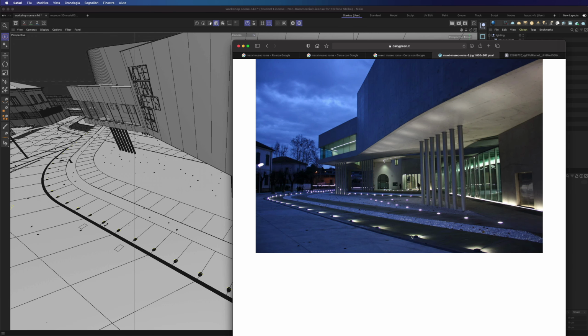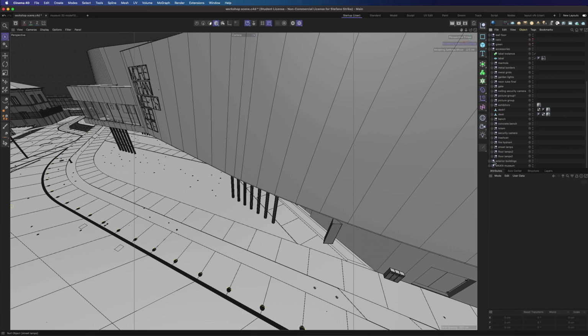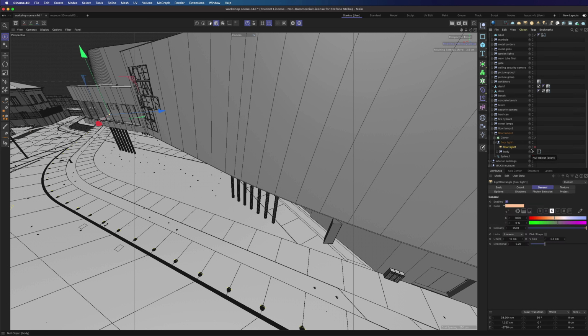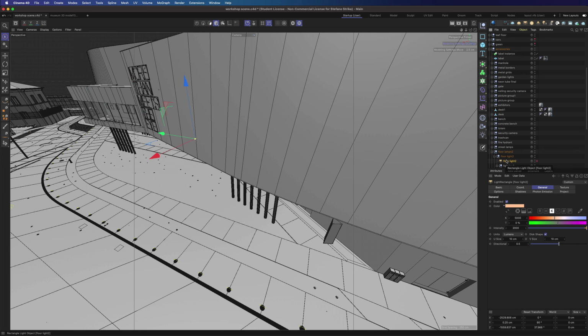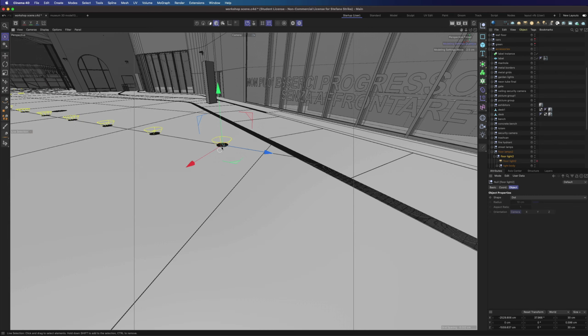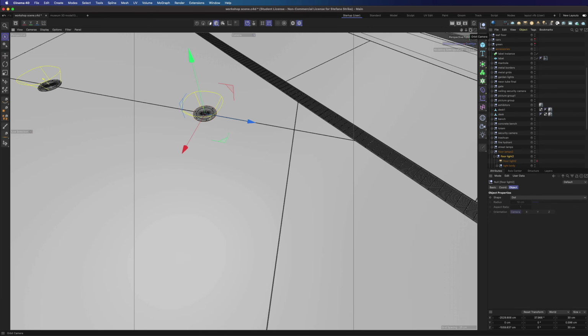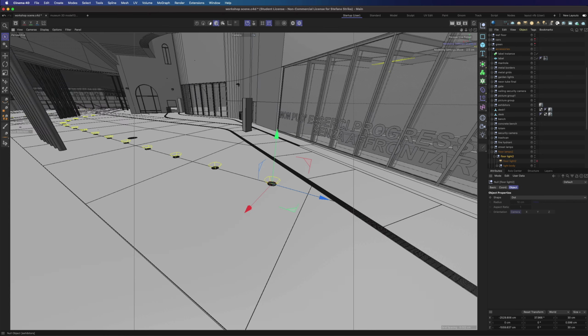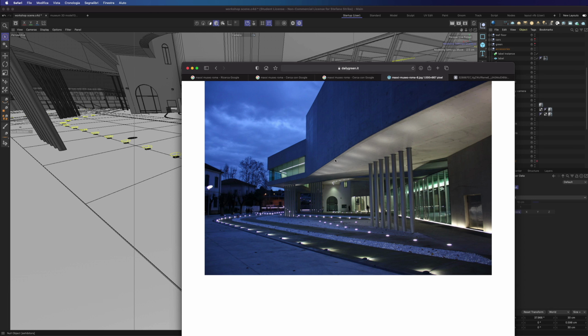Now we can see these floor lightings. In this case I always use a cloner to distribute them. I use 2500 lumens. I also use a little bit of directional light and always 5000 Kelvin degrees for the temperature. Even for these floor lights, I use pretty much the same values. Later we will see how to add these IES lights over here.